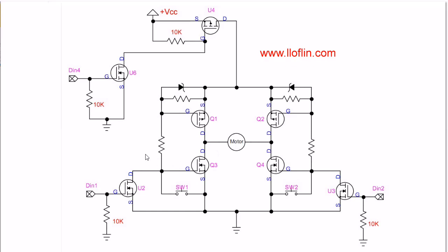So the sequence, again, for programming is you will turn off both inputs. This will enable the braking action of the motor. The motor will stop. You disable power, then you switch direction whichever way you want to go, and then re-enable power in those steps.